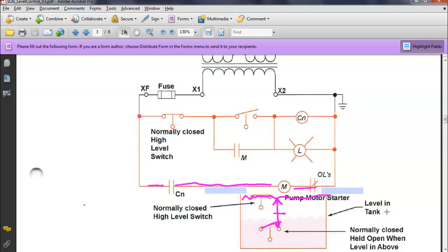Consideration. You got a compressor. If your air tool needs more air than your compressor can put out, then your compressor is going to run forever. Once it drops down, if your air tool needs more flow than your compressor can actually provide, then your motor is going to try to run forever. And those are not continuous duty motors. Those are what we call intermediate duty motors because they're designed to do what? Cut on and cut off. So if you run your compressor all the time, then what's going to happen to the motor on your compressor? You're going to burn it up.